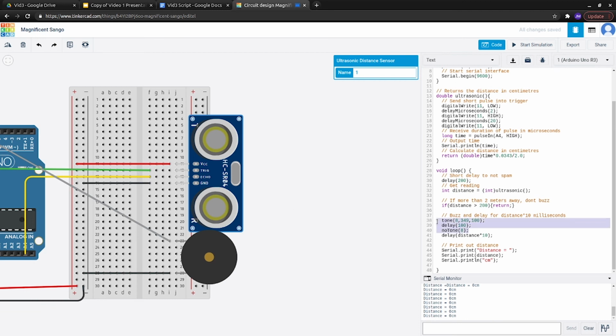These 3 lines are used to trigger the buzzer. The reason that noTone is used is because this delay happens to be very short, and a short delay might cause some residual sound if you leave it, and therefore we should use the noTone method to stop the sound. As you can see, the noTone method is very simple. It just takes in one parameter, which is the pin you wish to stop.